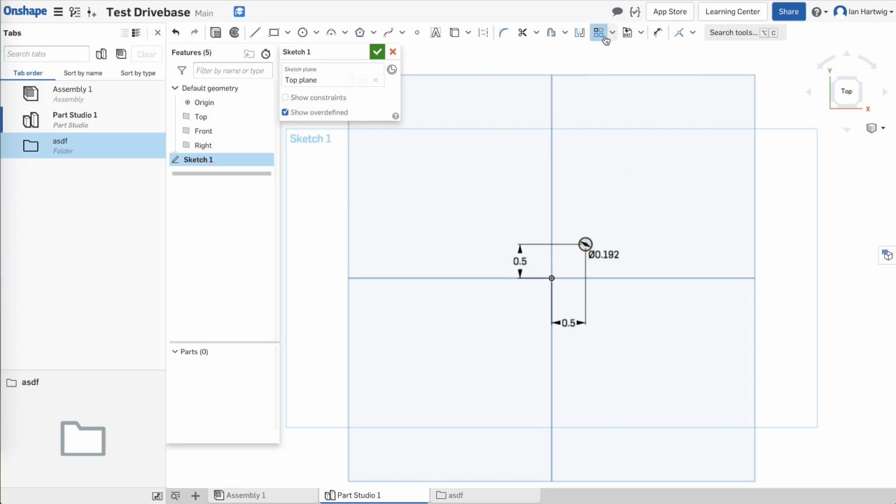So if we select linear pattern, and then we hit the circle, now there's a bunch of arrows that appear on the screen in either direction. The 3x, 1x is telling you how many of these you want in each direction. In this case, the 1 by 1 frame is going to go up, and the 1.5 is going this way.